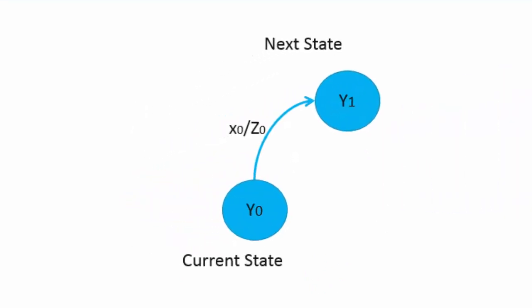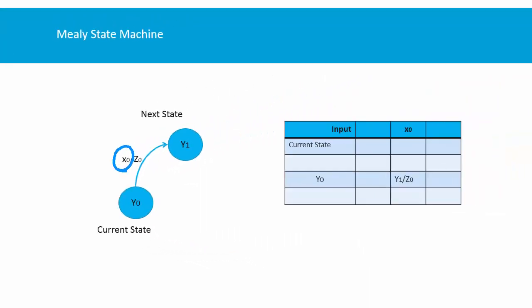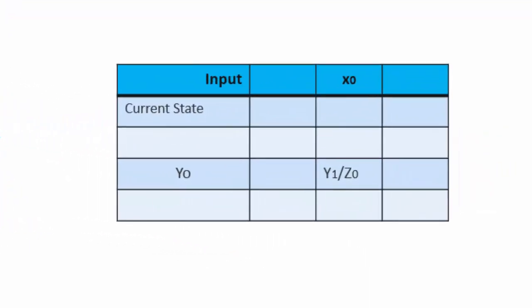Notice how we have two states, y0 and y1. And we have a transition, which is the arrow, telling us when we're going to change from y0 to y1. We change from that state to the other one given the input x. This is the state diagram. And this is called the state table.